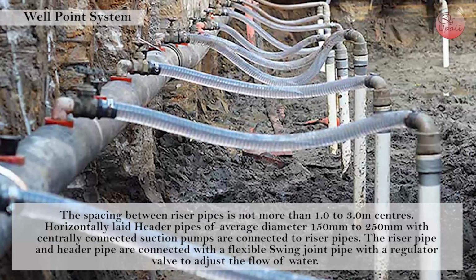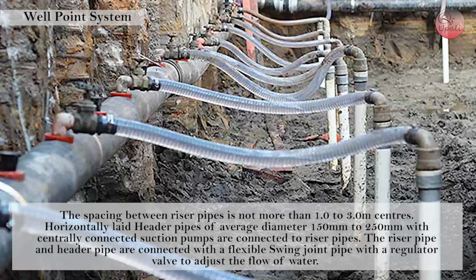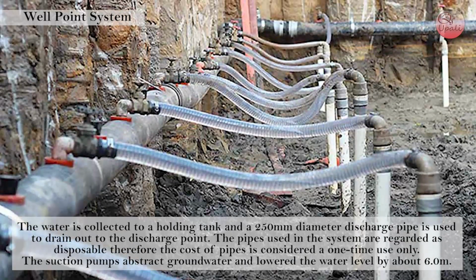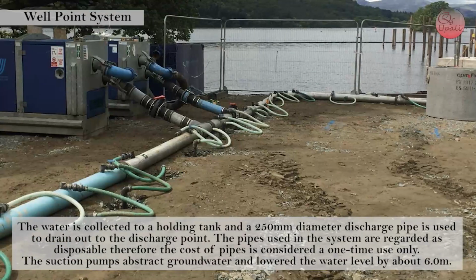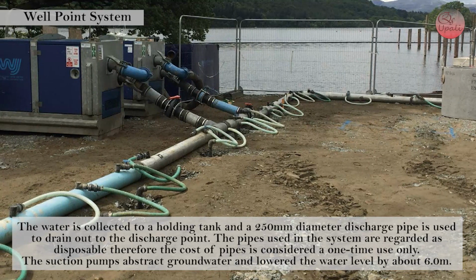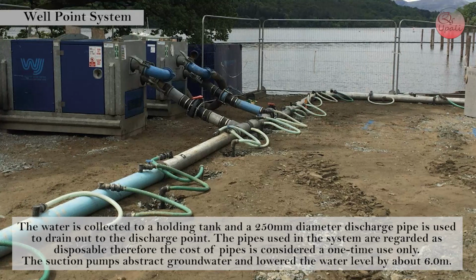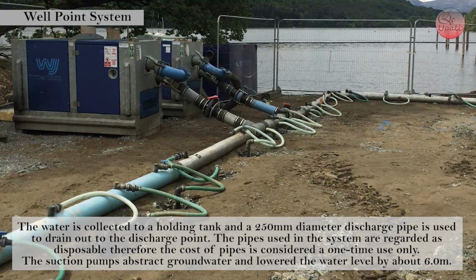The riser pipe and header pipes are connected to a flexible swing joint pipe with a regular valve to adjust the flow of water. The water is connected to a holding tank and a 250 mm diameter discharge pipe is used to drain out to the discharge point. The pipes used in the system are regarded as disposable. Therefore, the cost of pipe is considered a one-time use only.